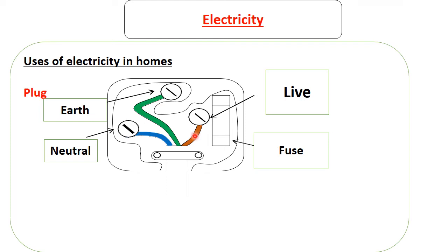To leak is to move away from the wires to go outside, such that when a person touches somewhere, they may end up being shocked. Whenever there is leakage current, the earth takes this leakage current to the ground. That's the purpose of the earth. It makes sure it takes away all leakage current, so that when a person touches this, the person is not going to be shocked.